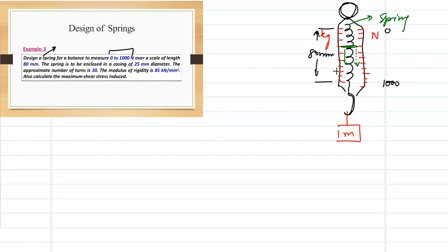The total deflection of the spring can be, so generally, if I will be more precise with respect to this drawing, you have a spring that is coiled like this, and there is a hook here, a pin here, and that is set as 0. There is a small hook over here, so spring deflection here is 0. So the pin is marked as 0 and 0 location on both scales. As you apply a load, the spring stretches, and due to the stretch, this pin goes downward. So the spring can deflect by a distance of 80 millimeter.